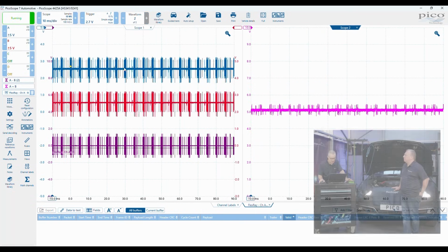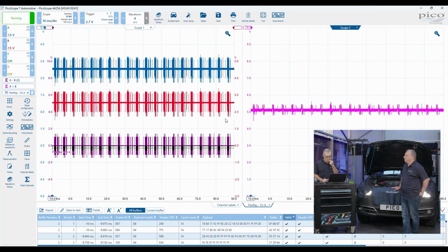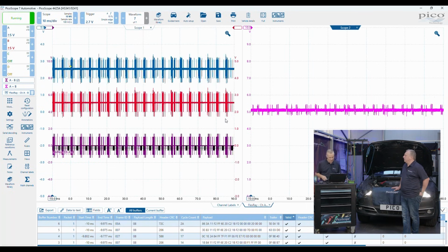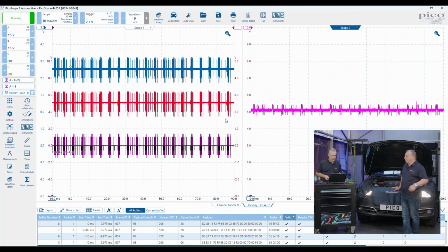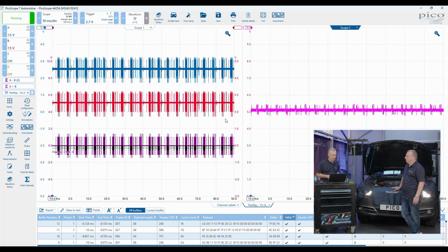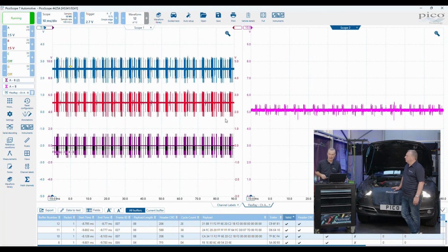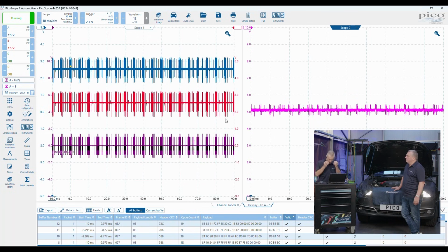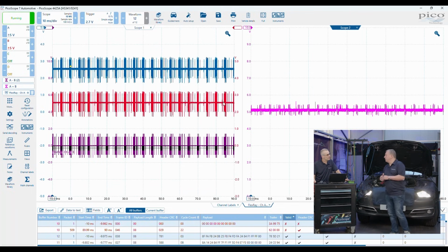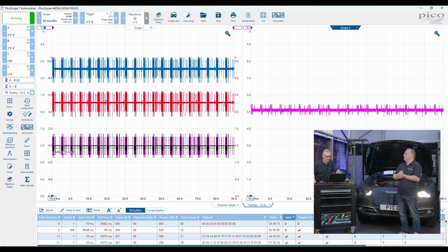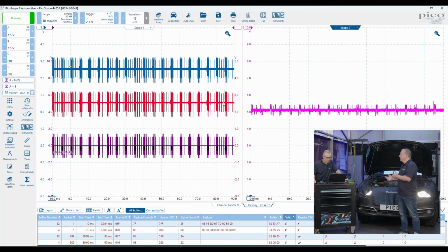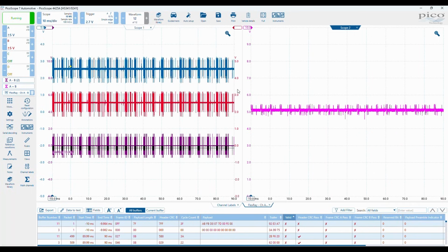And then we'll run PicoScope. So now we really are turbocharging that, as it were. We're probably using the resources on the PC and the scope. We have got channel A raw data, channel B raw data, the differential between the two, we're decoding, and now we've also got this channel that might help us with physical layer faults. And the only thing we've added to the guided test now is A plus B in scope 2. Because the maths channel and the decoder is all set for you, nothing to do there other than connect to the vehicle. We seem to be flagging lots of errors now, actually.